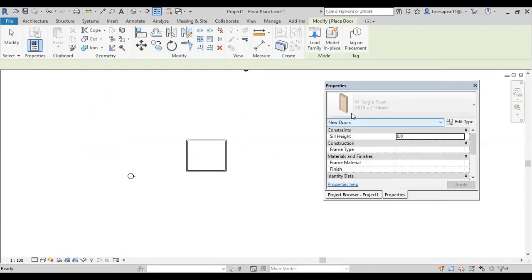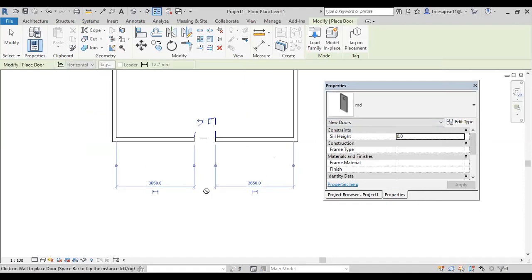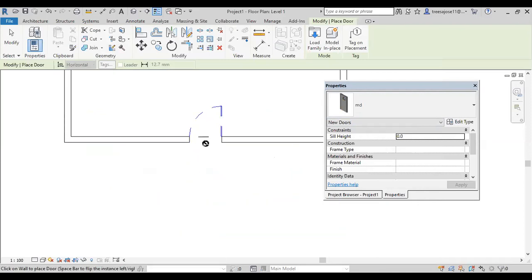Automatically that door will be here. Then whatever parameters, you can change the parameters. Actually, I haven't saved that glass hidden in. That is why the glass will be there. Better you save that one. Whatever changes you wish to do, you open that RFA file. Maybe sometimes your door looks like this, the same structure with some beadings and all. Whatever changes you do, then you save as and put it another name.